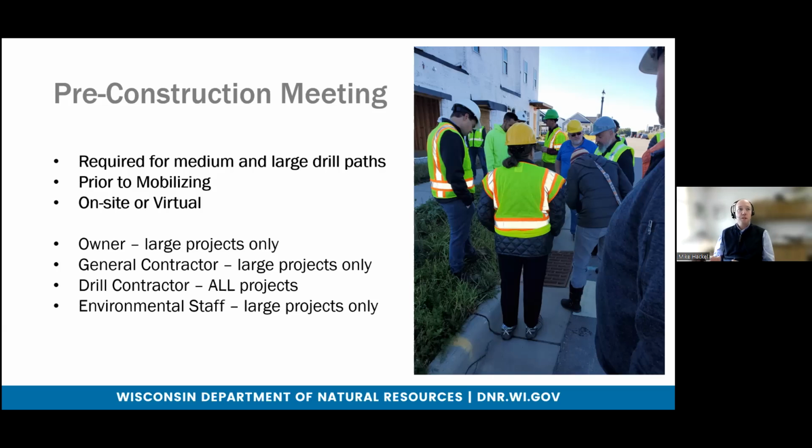Topics of discussion would be the location of resources that need to be protected throughout the course of construction, the plans for how you will be protecting the environment during construction, and the limits of disturbance for all the various components related to that construction, not only the actual drill path, entry and exit points, but also any access points, staging areas,